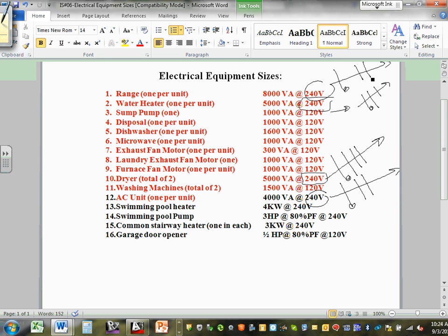Yes. How do I know? We wire tons of them. So here's my neutral. Did you guys understand how you circuit 240 versus 120? That's the concept of circuiting 240, 120. Yes, sir. So we are going to need 3 different home runs. For what? Well, for this. So there's the 120, the one hot and the neutral, and then there's the 240, two hots.